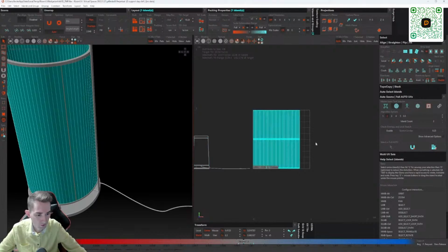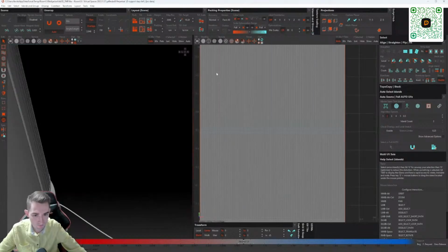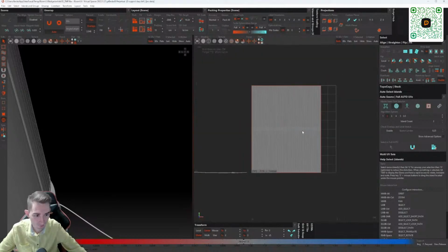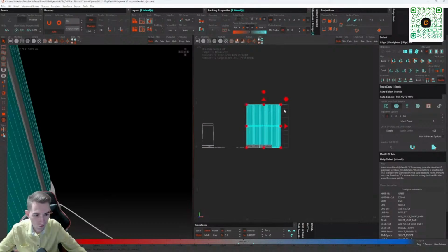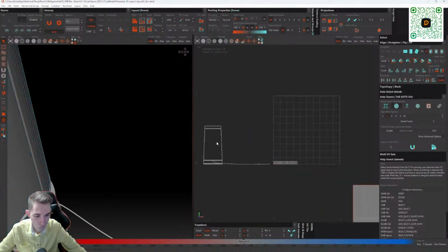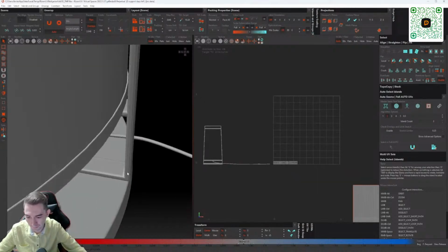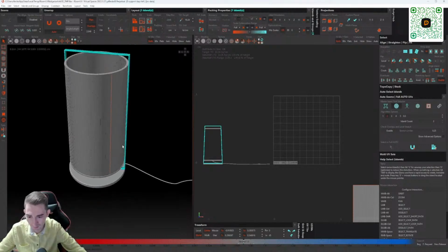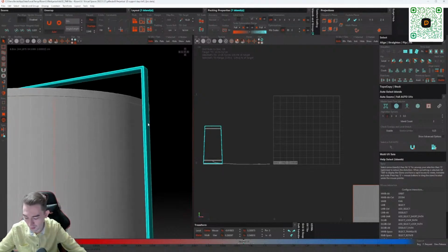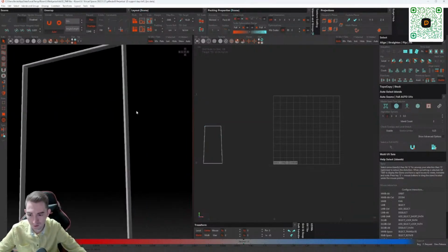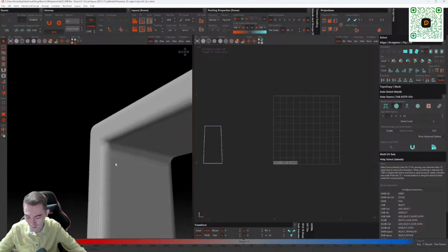Let's try the second method now. Yes, here the second method turned out well. In principle, there is some redness, but it is not strong. It can be ignored in principle. So, I pinch the tap and move it a little so that it does not interfere with us. So, now let's choose this element here, so that it is more convenient for us to unwrap it. Press the I key. This is isolation for us, that is, we isolate the object and try to divide it into parts.